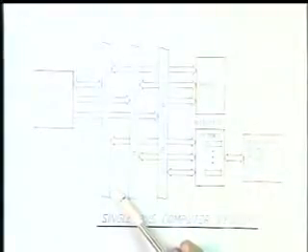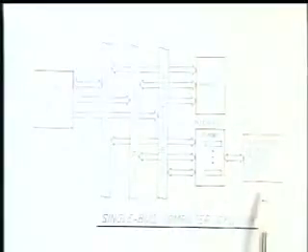And the address bus, as discussed, is normally a unidirectional bus. And the data bus, because the CPU has to read as well as write, has to be bidirectional. Now, the control lines are basically to decide whether the data is for the memory or for the input-output devices. Because it is a single bus computer, there must be a method to differentiate, or different control signals should be available, which will tell when to access the memory and how to connect the peripheral devices.